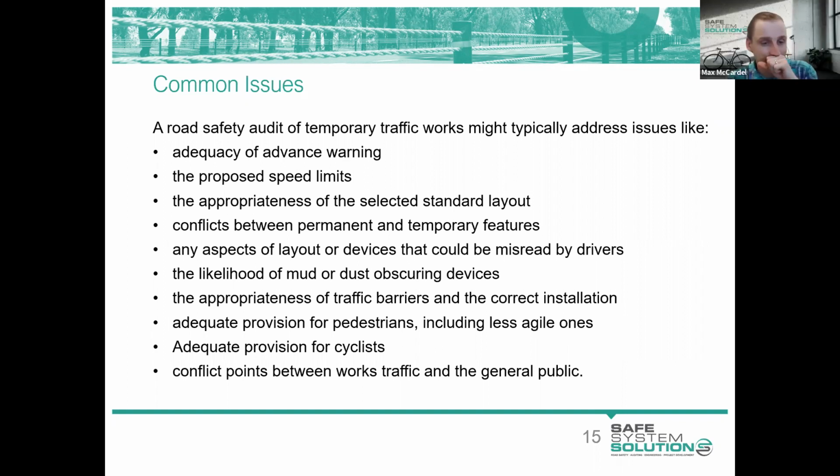No problem. All aspects of the layout or devices that could be misread by drivers, have we got that understanding? That's what I said earlier. That's why it's great to have that independent person reviewing these sites. Have mud and dust obscured the devices, especially at night time, making it so that you can't read them?